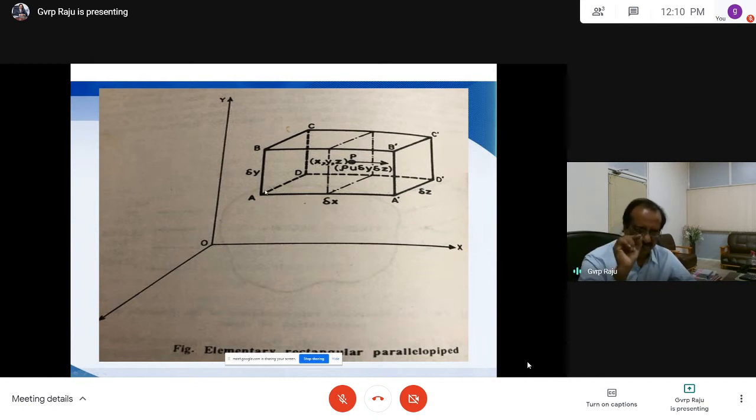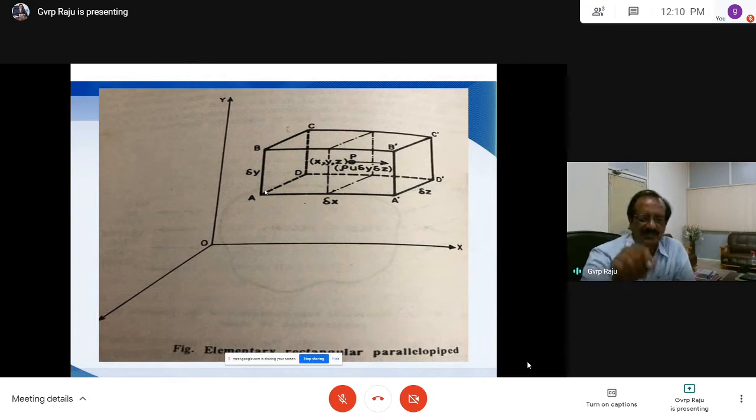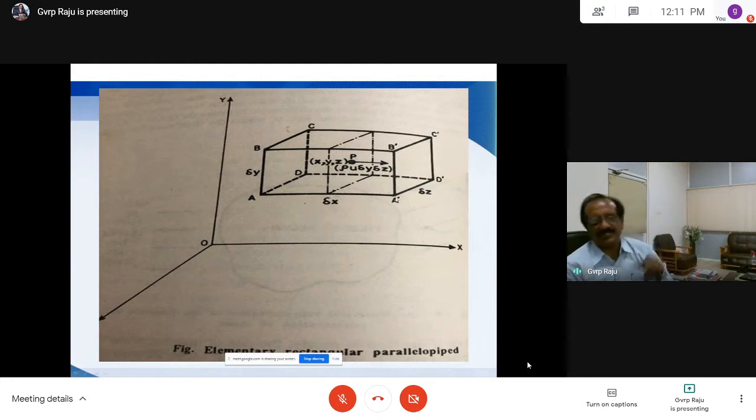That is the equation, and the same procedure applies to each and every derivation. Sometimes you may be asked for a small derivation, which is why I am stressing this. Similarly, for outflow we have the mass rho u dy dz at the center, and moving toward this side we add a positive sign. So outflow is rho u dy dz plus d of rho u dy dz by dx into the distance dx by 2. That is inflow and this is outflow. For steady flow, inflow is equal to outflow.